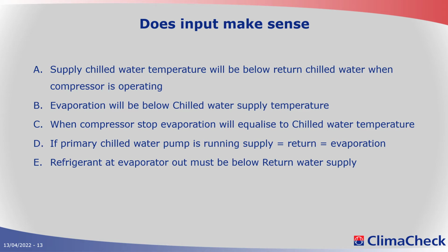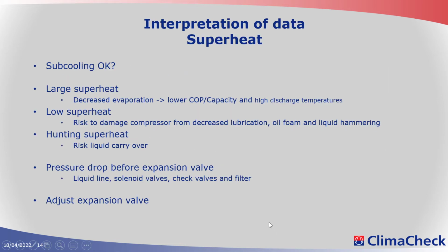We cannot get the suction gas coming out of the evaporator to be warmer than the incoming air or incoming water. So we have these rules on how the system should behave. So always take a look at the data to make sure it makes sense, that all the sensors are the same, and all the sensors are correctly applied.